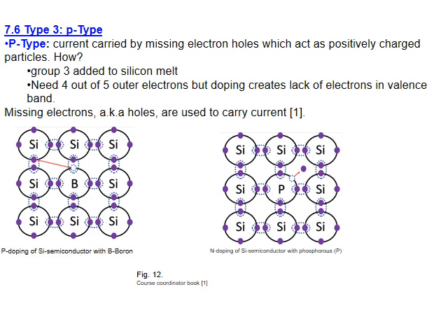An example for n-type, as you can see here, is phosphorus. For silicon we have 4 electrons in the outer band, and if there is another silicon atom nearby, it is connected with it in a bond, and then with another atom and another atom. But when we put phosphorus here, this electron connects to this electron of the silicon atom, and this one with this one here. But we have an extra electron because P has 5, not 4. So this electron will keep moving around this network, from place to place. So we create movement of electrons, we create electrical current.